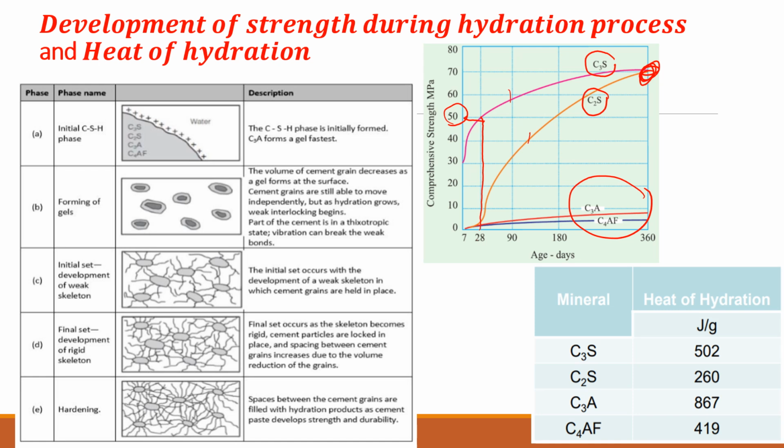It's the same as, you have caster sugar and the normal sugar. Caster sugar is dissolving quicker, isn't it? Because the surface area is high. So likewise, if you have a cement with tiny particles, then the reaction is faster.